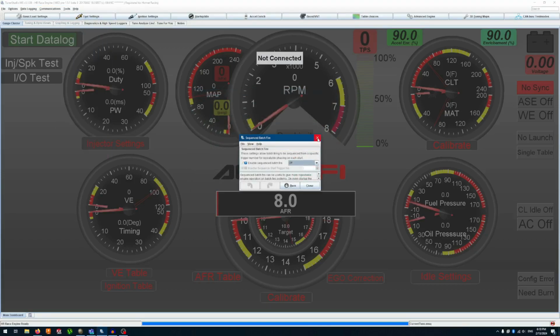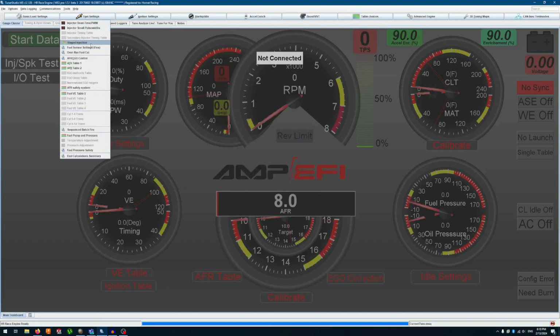Batch fire: you can batch fire if you want, or sequential fire. Honestly, I wonder which one even makes more power or wastes more fuel. If you batch fire, you're cooling the valve, and fuel evaporating off the back of a hot valve is really well atomized, and a poor spray right next to the valve entrance is not. So I would not be dead set on sequential always being better. Sequential is better when everything is done right. Don't think that you did everything right.